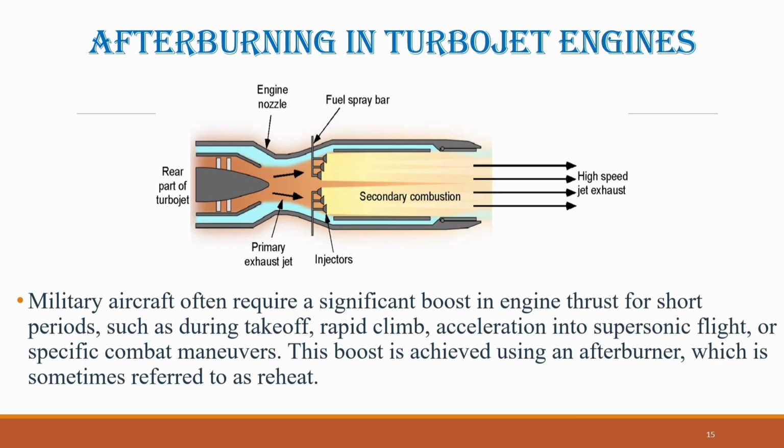The engine's core exhaust contains sufficient excess oxygen to support afterburner combustion, so no additional air inlets are needed. When the afterburner is lit, the resulting exhaust flame is often visually dramatic, partly because the flow speeds are supersonic and the hot gases form diamond-shaped shock waves in the tailpipe.